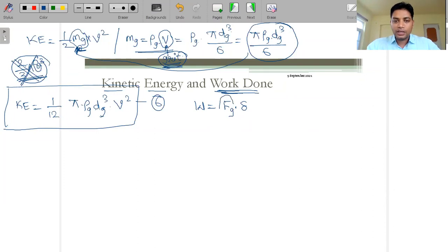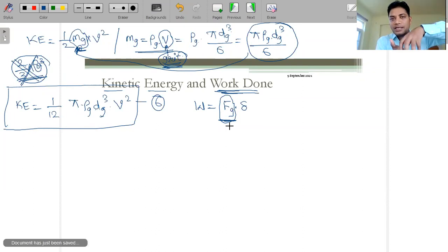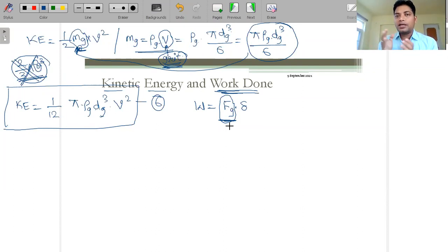Now this Fg is basically the force, but I do not want to carry this value further. So I can replace this value. How? Force is equals to the strength of these abrasive particles impinging over the workpiece surface, times how much area is covered. Simply, that will be equals to pressure into area, or strength into area, because here we are considering the strength part.